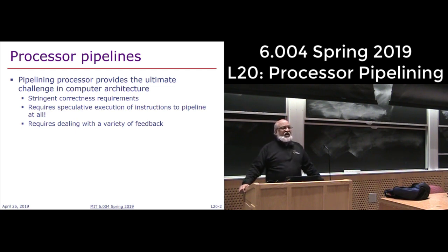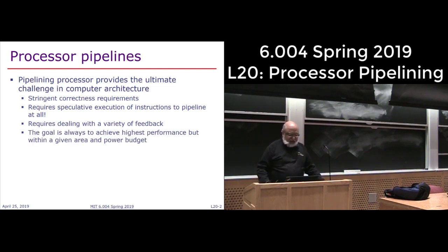And as you will discover very quickly, processor pipelines have feedback in several places. And whenever there is feedback, if you insert one extra FIFO, one extra register somewhere, it can change the semantics. So that becomes a correctness argument. Are you still preserving the semantics of the ISA as defined by the multi-cycle implementation you did?